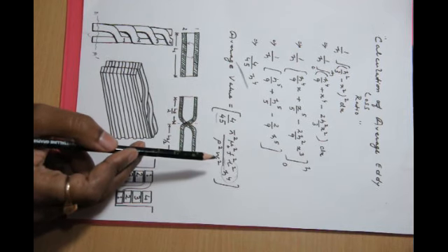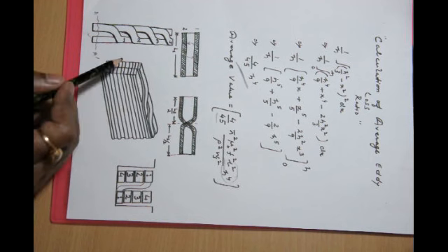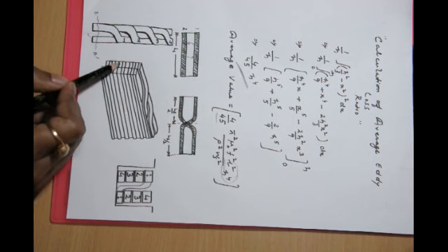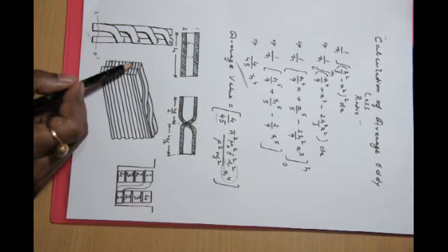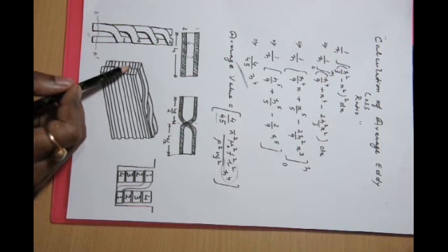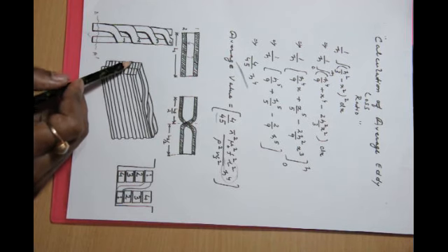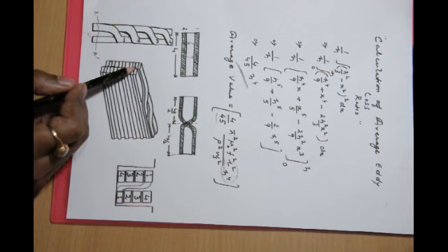Instead, what we will do is we shall subdivide the whole conductor into smaller divisions like this, insulated from each other, so that the same amount of total current may be carried, and at the same time we reduce the losses because B and H are reduced for each individual subdivision.